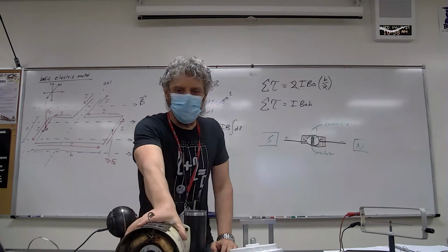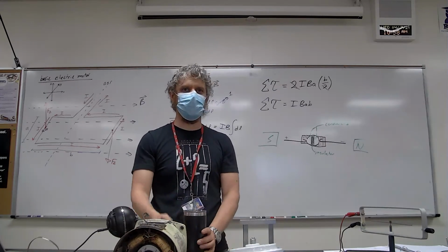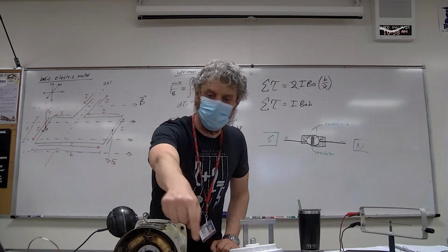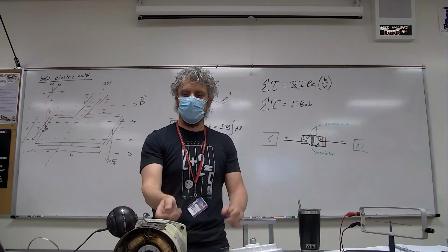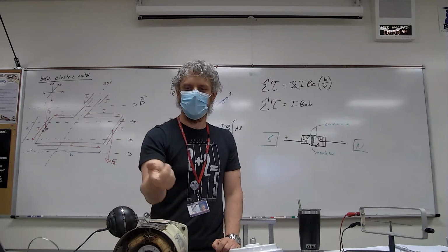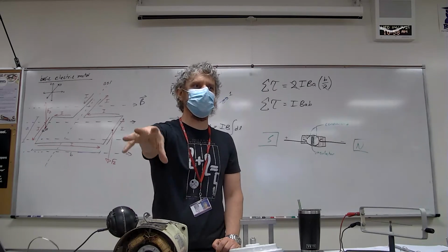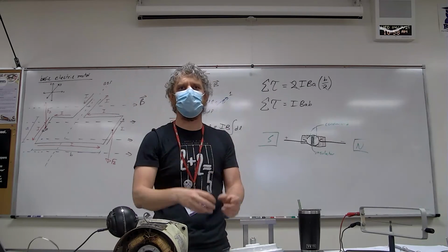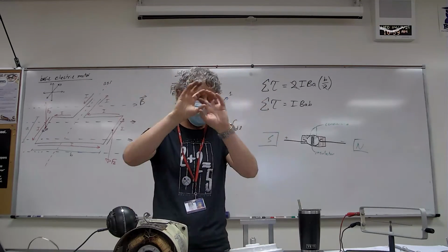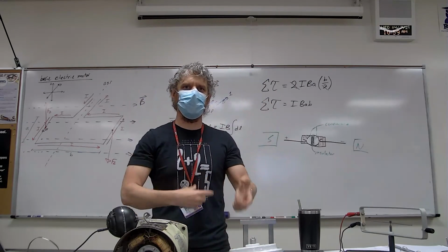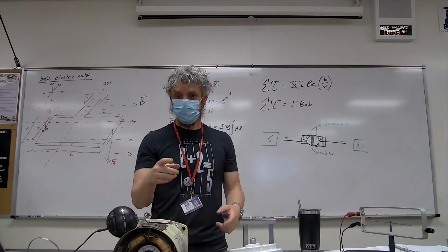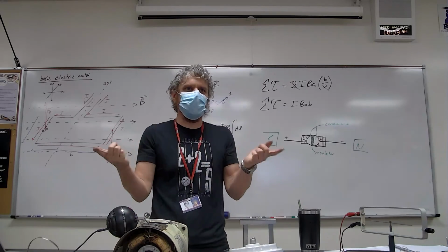And I like bringing in my pool pump, well, at least this year, because it crapped out about 2 weeks ago and I had to replace it. But if I open it up, you look in your pool pump, it's just the center post, it spins, right? And that happens because you have a central rotor that's a magnet surrounded by a stator, which contains all the coils of wire, and it's the interaction between those two. And this goes to alternating current.